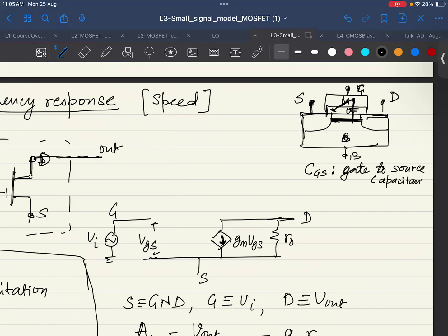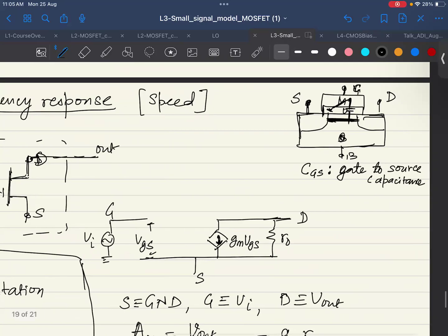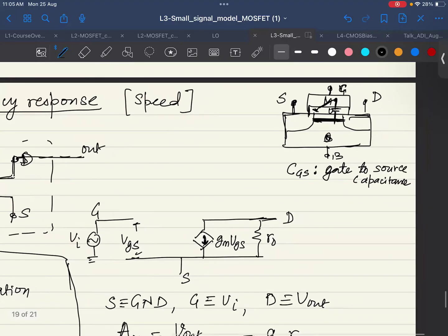So whenever somebody is wondering whether, in a physical structure, there is a capacitance or not, one way to see it very clearly is from the definition of the capacitance itself. If there is a capacitance between two nodes, Cij, the definition is that there is a change in the charge at node J with respect to the voltage at node I, because you know Q equals CV, right?